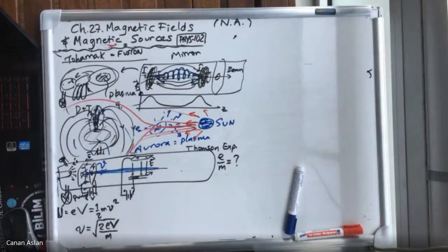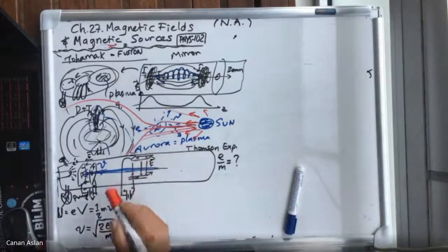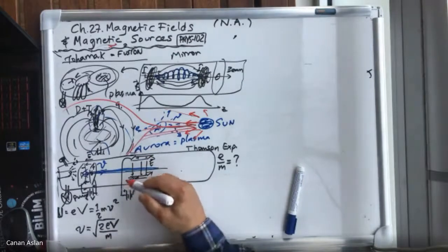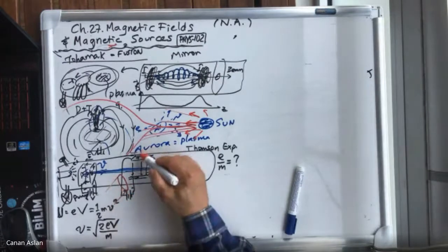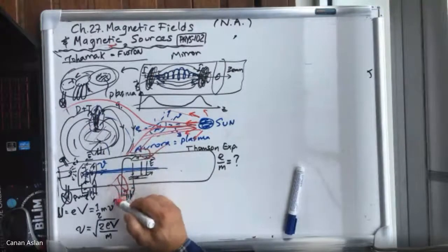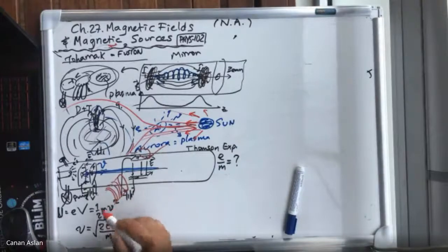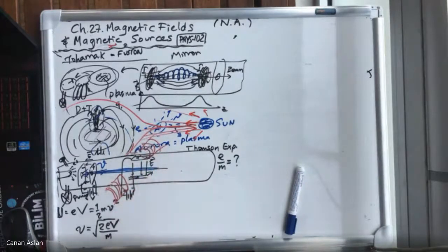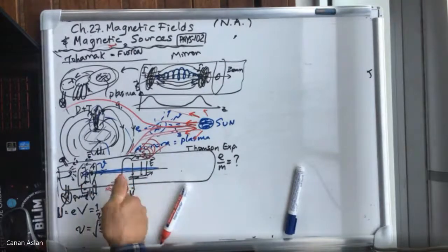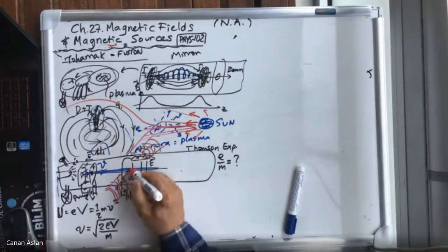Now we can also apply a magnetic field totally in the perpendicular direction by putting two coils, for instance. I can put one iron yoke here and another one there, and then put some kind of wire windings, some number of windings, so you can create an electromagnet. And depending on the direction of the current, for instance here, if the current is moving this direction, this is north, and the magnetic field lines will go out.